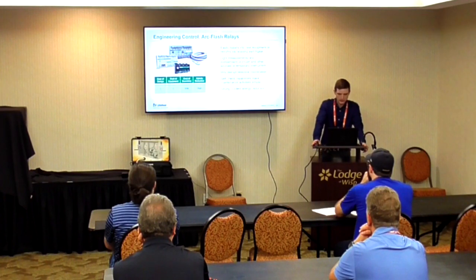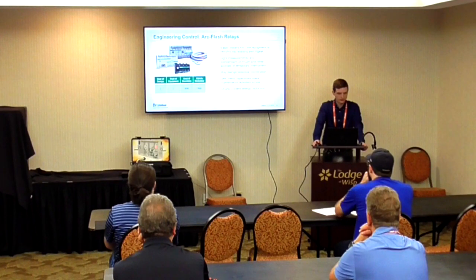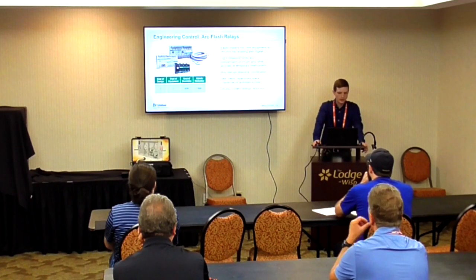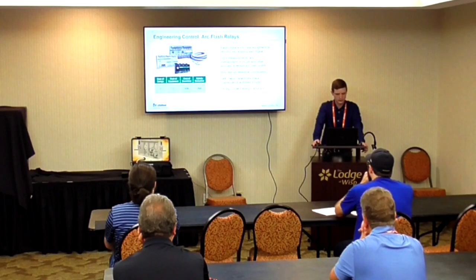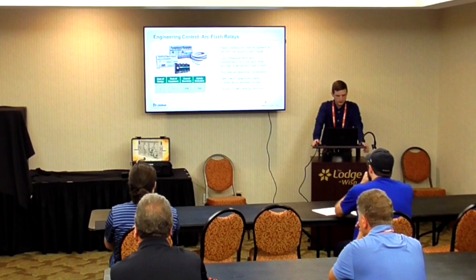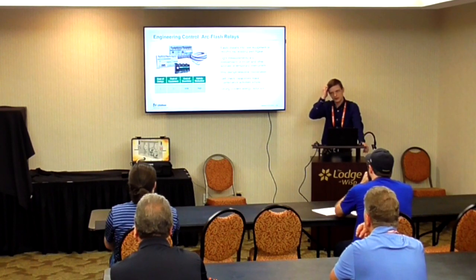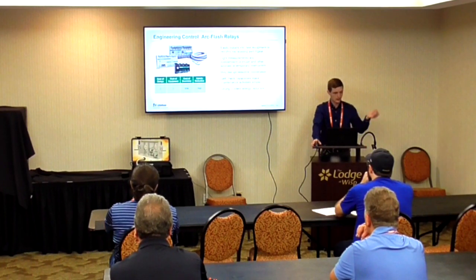This is a standalone piece of equipment, so you're not actually tying it into your electrical system. This is only watching for light for most of these. Some of them have some additional features, and we can get into that a little bit later. But that means that you're not having to shut down your system and actually rework some of the architecture to install this. These are also easily integratable by SKM, EasyPower, ETAP, any of those modeling softwares that I mentioned before. All of these arc flash relays are already included in those modeling software, so it's very easy to punch in and say, okay, I've got 24 calories, now I've got 4, I can move about my day.